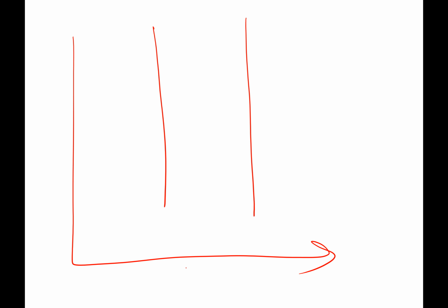Prior to this, when we've looked at a plane wall, if we draw the temperature profile, let's say this is x and this is temperature, we know that at steady state the temperature profile through a plane wall will just be straight. Mathematically, the way we've treated this is as a sudden jump in temperature from the surface of the wall out into the bulk, and similarly for up here.